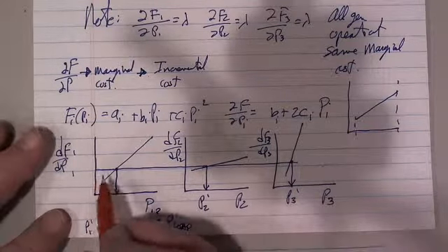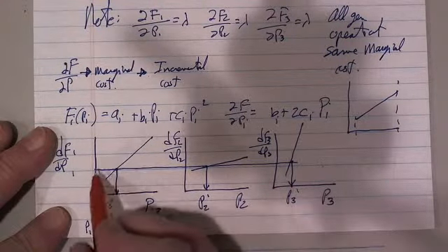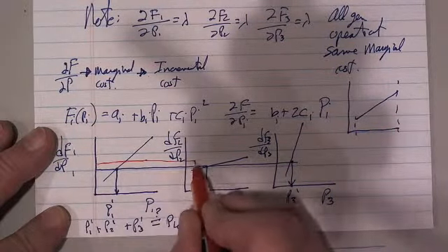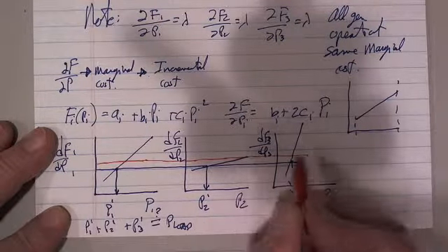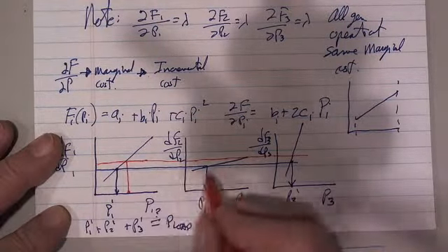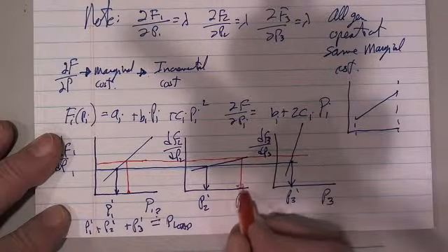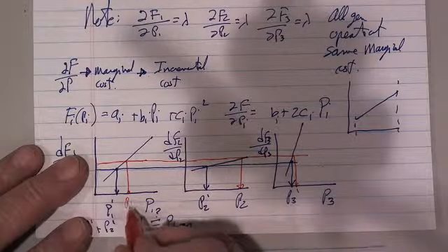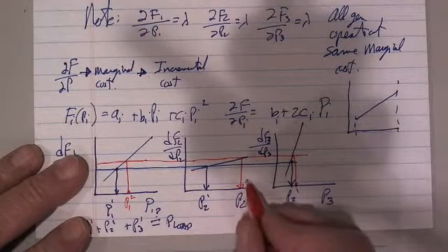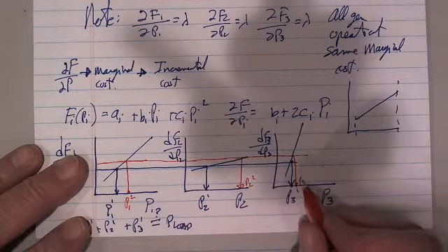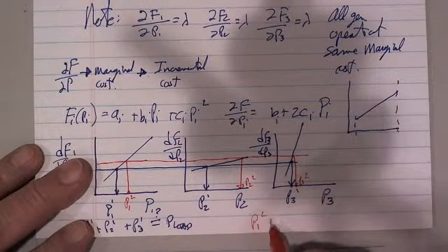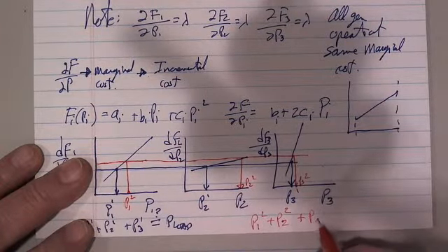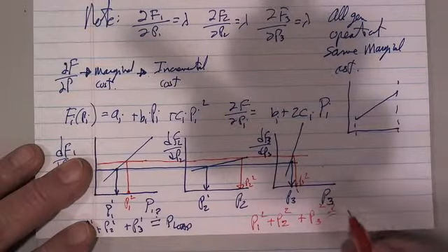What I should do is take my ruler that I have here and just draw another line, the red line, across like this. And now I get a different set of intersections. Notice that this one really zooms up. This one hardly moves. So now I get P1², P2², and P3². So now I can say P1² plus P2² plus P3², and I can compare that to P load.